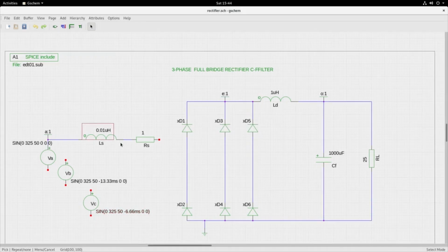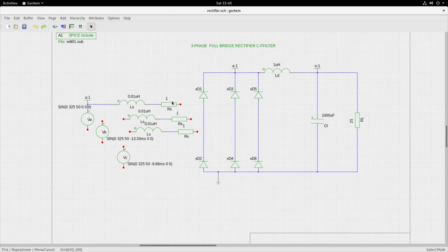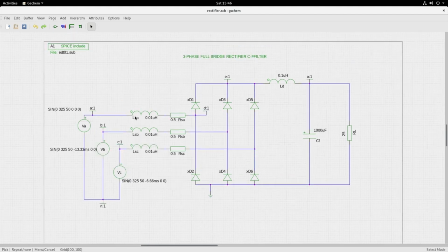So you will have that. You will have to duplicate these and connect. Control copy, control paste. Copy, control paste, control paste. So let us rearrange and connect this. So after rearranging and then properly connecting, the entire 3-phase circuit looks like this. So you have VA, VB, VC. These are phase voltages with respect to the neutral. VB with respect to the neutral, VC with respect to neutral.